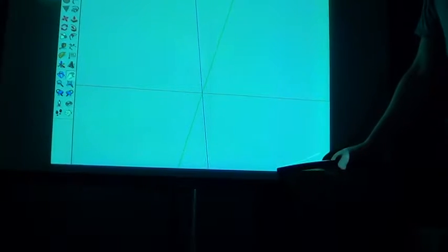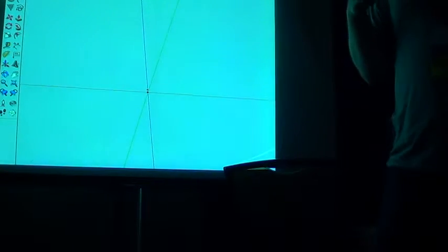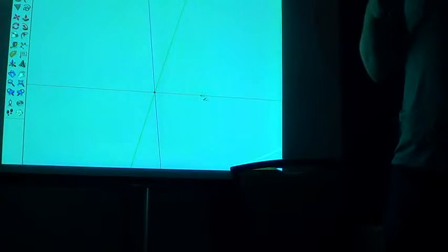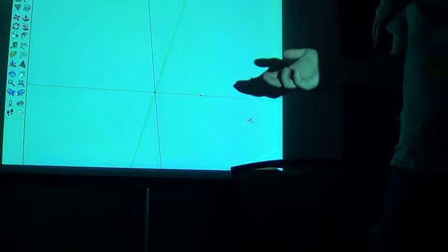And then there's PVA, which is a water-soluble material. So if you've got two nozzles on your printer, and you want to print parts that interlock, you can print PVA in between them, and then soak it in a hot water bath afterward for a few hours, and it dissolves. And so then you have parts that move inside each other that were printed in one shot.